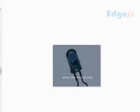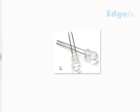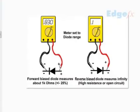In order to ensure that, what one has to do is take an IR diode, and as usual they will have a shorter leg and a longer leg, and you have to test it like a diode that we have seen in earlier cases, and the IR diode will show some indication as what we have seen like a diode. As we said, the LED, IR LED, all of them are in the diode category, and they will show some reading.